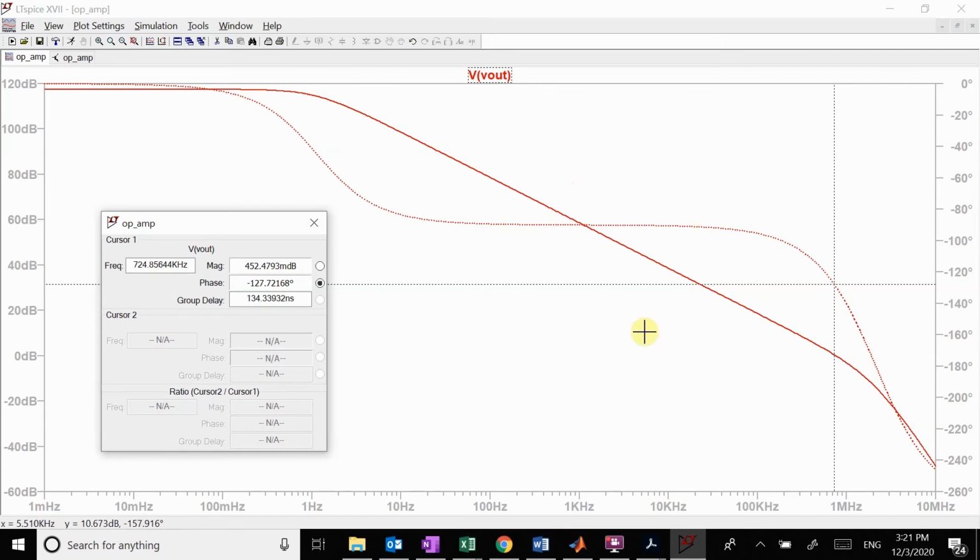Now, an op amp has multiple corners. What you see here is that they put most of their corners at a high frequency and put one corner fairly low in order to attain this feedback stability that we've talked about. So you have a good phase margin and a good gain margin. To say that again, here's one corner that's really low, and then all of the other corners are out here that are fairly high, so that this op amp is always stable.